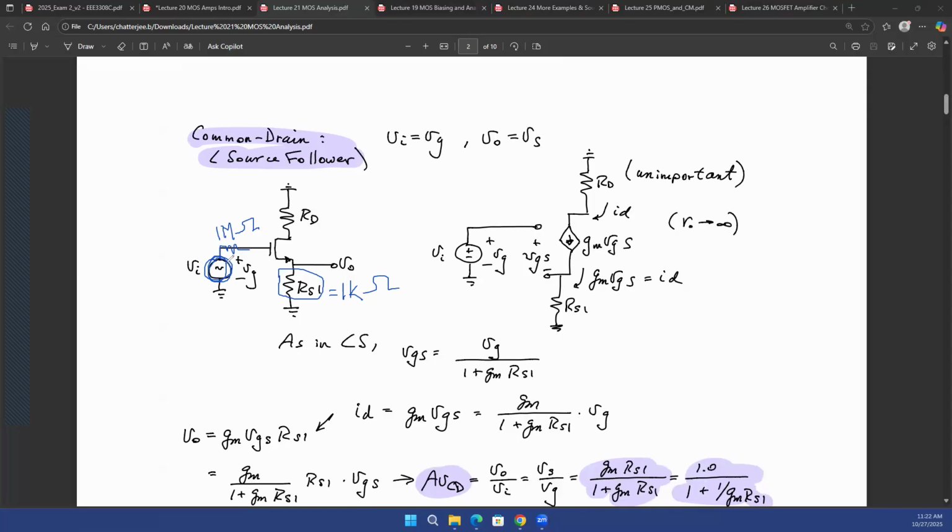Again, in this case, we are assuming that the input voltage source is ideal, but it can be generated by another MOSFET-based circuit, and it's always possible that the output resistance of that MOSFET-based circuit is not very low. Ideally, any voltage source should have a zero output resistance. But MOSFET does not have a zero output resistance. MOSFET has infinite output resistance. We know that, right? So if you're using a MOSFET-based circuit, it is possible that your output resistance is high, even though you're trying to use that as a voltage source.